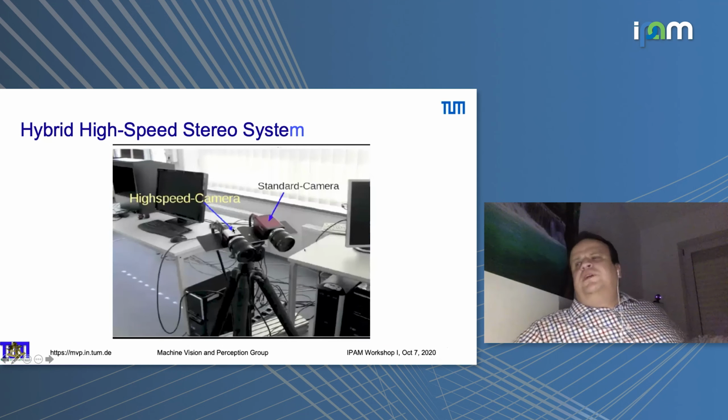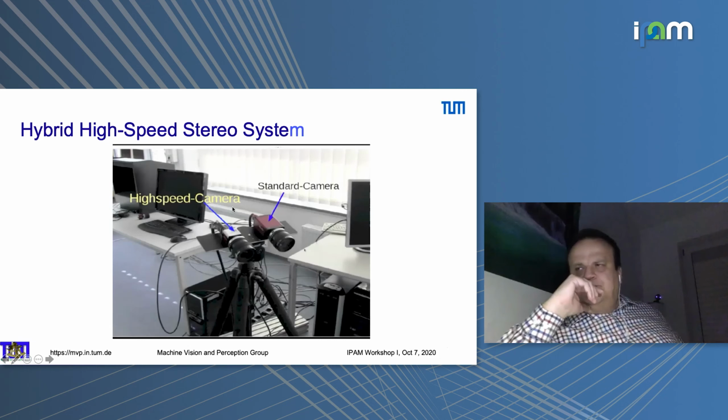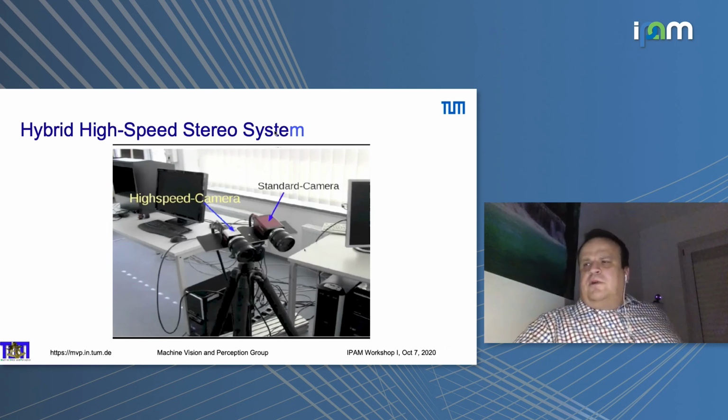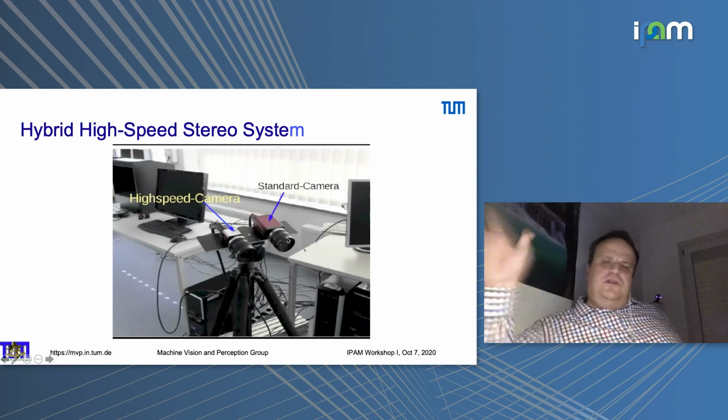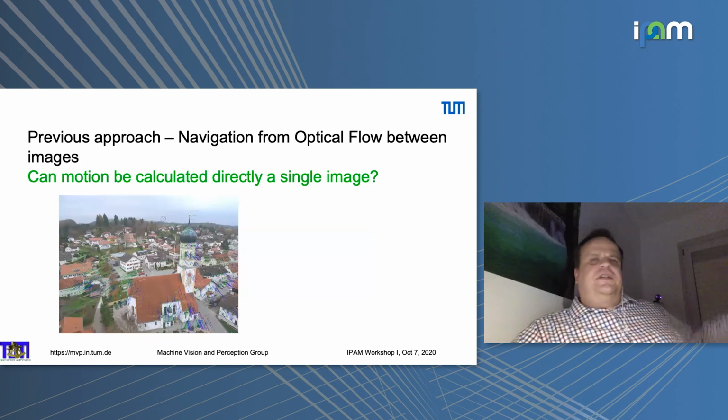And now to deal with the scene, we want to have very fast observation. I've shown you already that we can navigate our system with very high frequency, 120 hertz. But from a monocular camera, it's impossible to get depth information. You get a 3D model which is up to scale. There is an unknown scale which needs to be resolved somehow. And in my system, the scale is resolved by a second camera, which occasionally takes a snapshot of the scene and injects the scale into the system. And this allows us to make fast observations of the surrounding world.